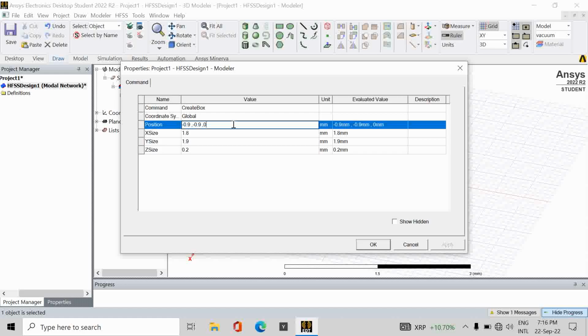Regarding the dimensions of the substrate for the 3.5 gigahertz antenna, I'll consider them parametrically, so that if I want to change a value again, I can change it later on. If you give a numerical value, you have to calculate each and every value again and again. By using mathematical equations, it will be easier while designing.